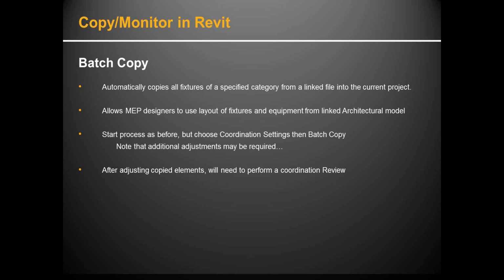Somebody passed along, Dan pointed out that propagate extents does not work for dependent views. To be honest, I haven't tried that, so I'll just share that with everybody. Propagate extents does not work for dependent views. Now I'm thinking about that and why it wouldn't or why it would, but yeah, I'm going to have to play with that after this is over. But yeah, I'm thinking of the dependent views. They have their own crop region, so I'm just thinking how that would affect it. But yeah, I'll have to play with that.